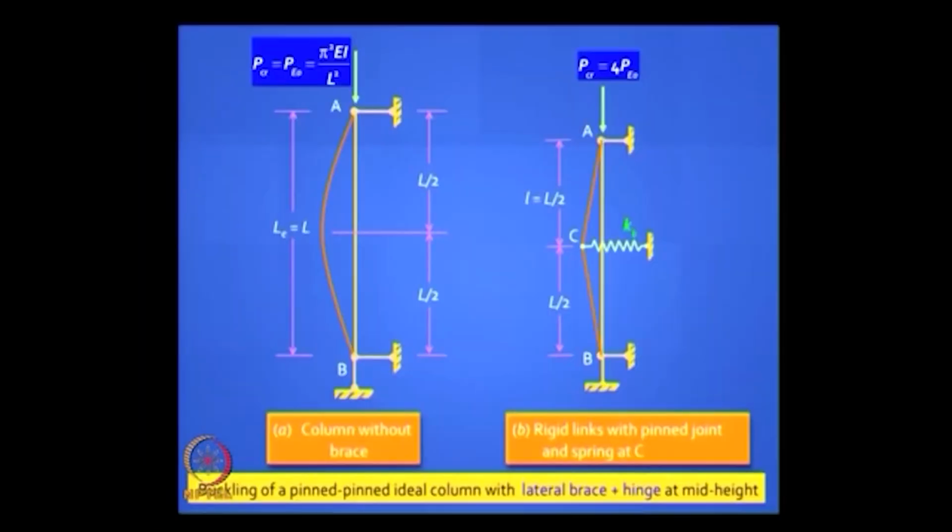So you can prove, you don't need to do this. You have to provide a minimum stiffness for that brace, and that will guarantee this for you. Let's check it out. Let's say you provide a weak brace, low value of KB. How would you think it will buckle now? If I put a hinge there, then definitely it is going to buckle like this.